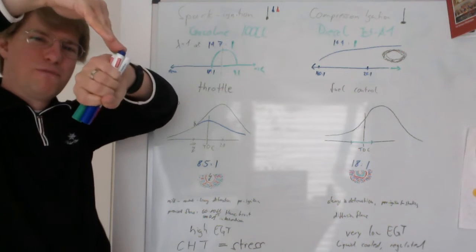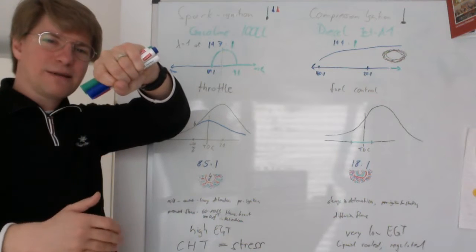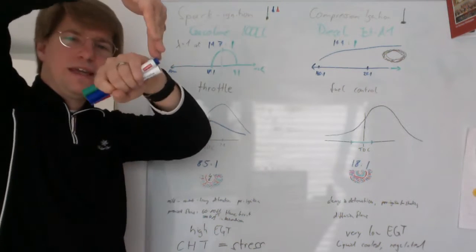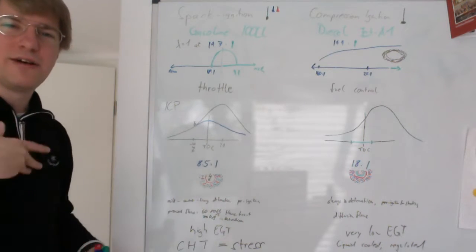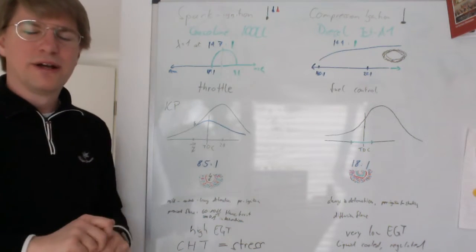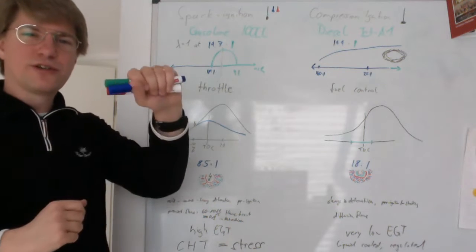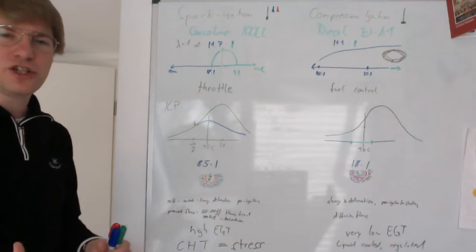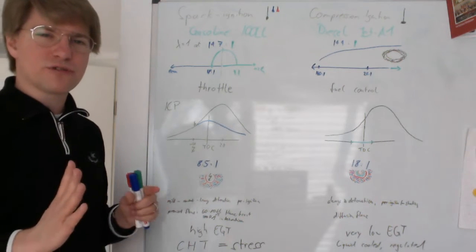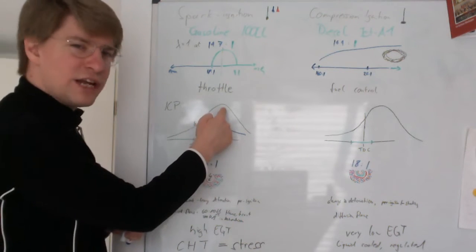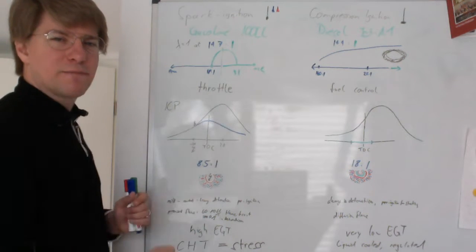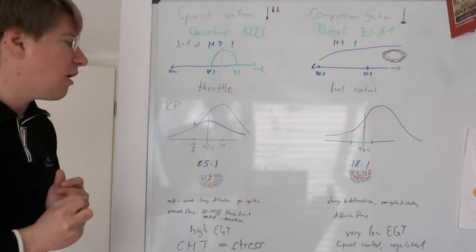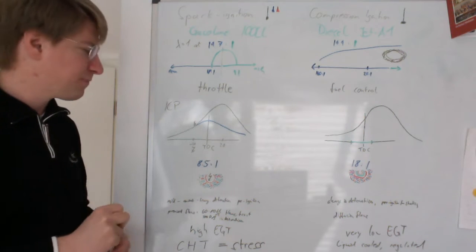It cannot really move the crank, whereas at about 20-30 degrees after top dead center, the piston can really convert this energy into mechanical energy, turning the crankshaft. So the timing of the spark plug is such that if the combustion process goes orderly, we achieve the peak internal cylinder pressure from the combustion at around 20 degrees after top dead center, where we want it.